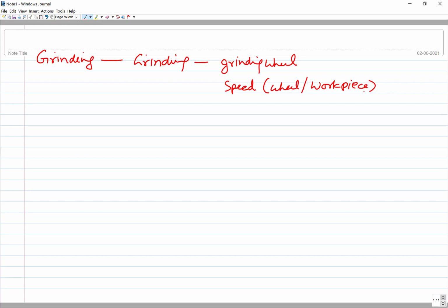You see, the surface condition, the flatness and the smoothness are also significantly determined by the rigidity of the system, how robust the system is. If the system is vibrating, then a lot of irregularities, roughness, and poor surface will be produced.